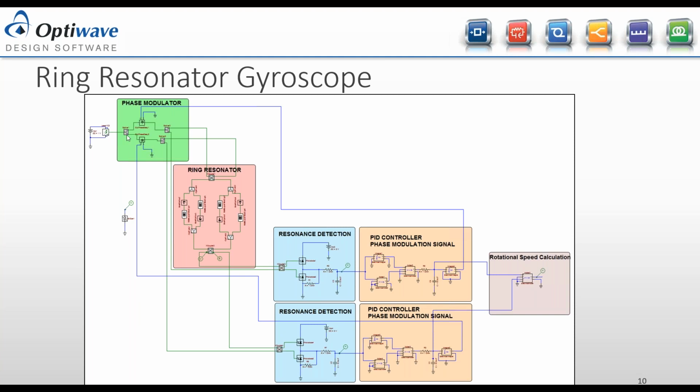What it does is create a phase shift in the optical signal, and depending on the rate of change, this phase shift will shift the frequency. Let's say if you have a linear increase in phase, this will translate to a shift in frequency. Depending on whether it's a linear increase or decrease, you will get an increase or decrease of frequency. Then we have our ring resonator here.